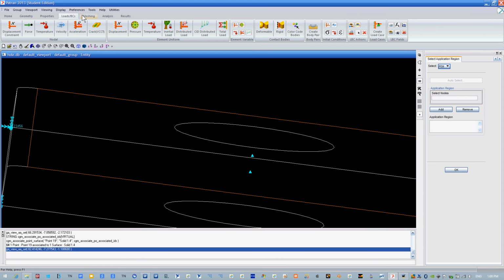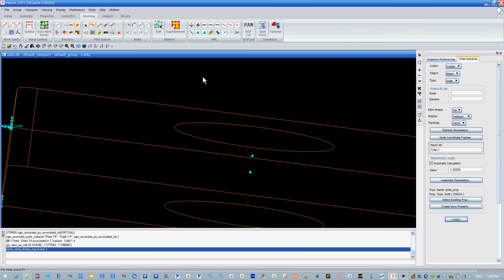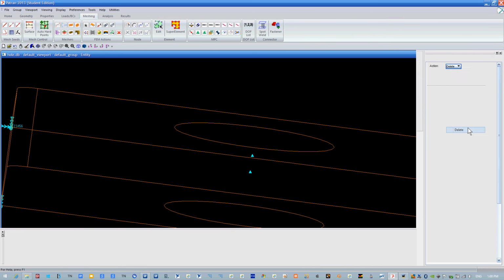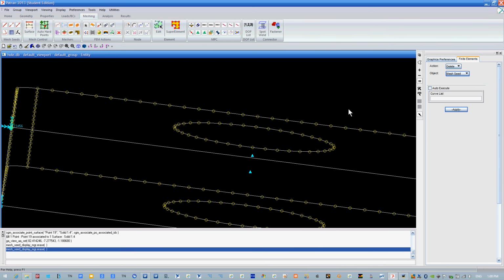If there's any questions, please just ask them. So once you have the geometry, once you've got the points identified where you're going to eventually want to apply the forces, you want to create the mesh. The reason our mesh disappeared is because we had too many nodes in this. We're limited. So that's why the mesh seeds are incredibly useful for this. Otherwise, just go wild and make, I don't know, millions. Delete mesh seeds.